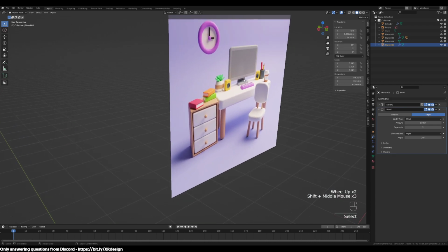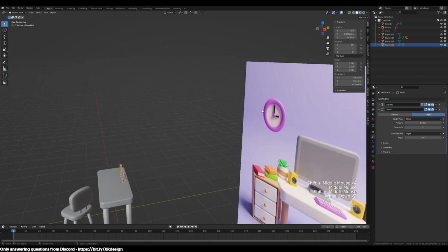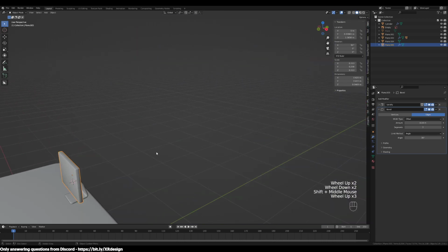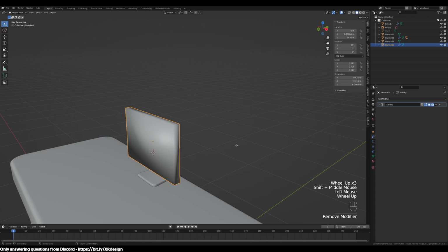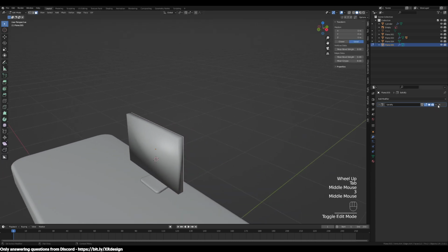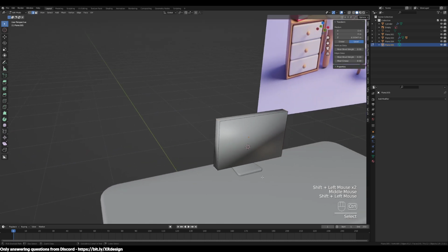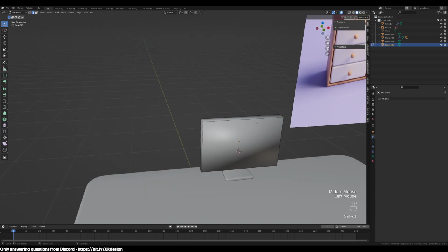And then just looking at this, it does look a bit rounder on the four corners here. So if you wanted to, you could remove the bevel and just extrude it the way we did, and then tweak these four corners, round it this way first, and then round the front and back.